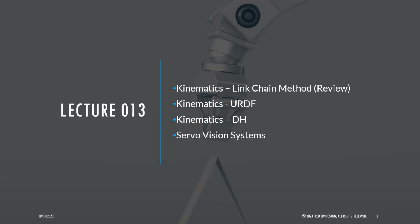There are some pros and cons in each of these methods. The link chain is easier to visualize and see. You're just doing rotations and translations. The URDF gives you the capability to add CAD meshes. You can add friction coefficients, mass, and color, and you can have more of a visual effect that you can't get in some of the other systems. You can also put in joint limits.